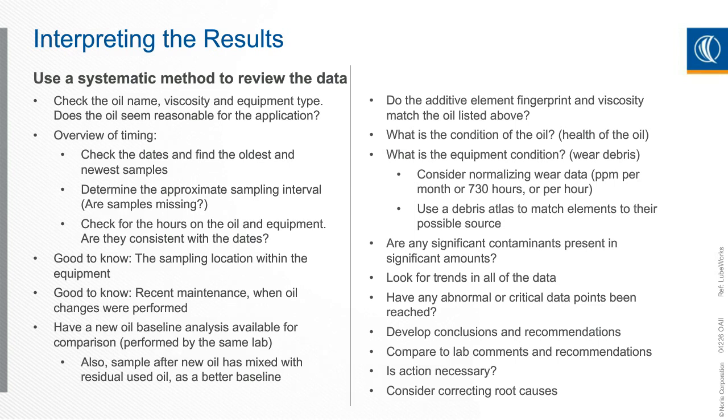Overview of timing: check the date to find out the oldest sample, the newest sample, and see what the trends are. You want to know what the sample location is. Was it a good sample location or a bad sample location, whether it was from a return line or a reservoir, or maybe it was done in a procedure with a certain maintenance tech that is less familiar with the procedure, and that could help understand why that result was different.